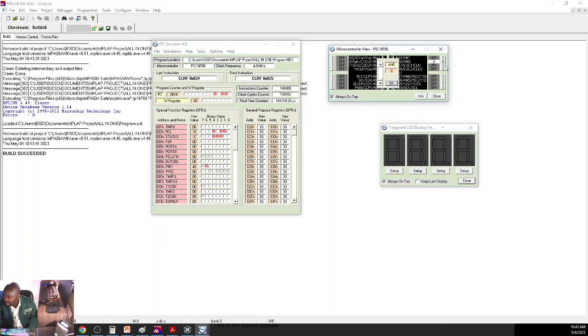Let's just see. High speed, I want to see if I'm going to successfully display. Now, if I have 10 on ADC, my results will be 100 will be 0, 10s will be 0, units will be 5. See, there's 5 there. 100s, 10s, units, right? And if I change this upper and upper, let's say I make it 30, my temperature has to be 30 divided by 2, which is 15. Meaning 10s will have 1, units will have 5. That will be 15. 100s are still 0.